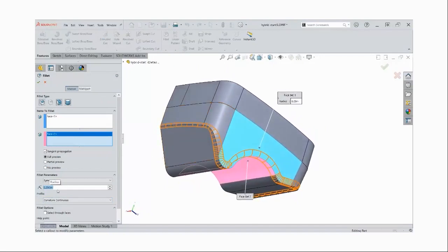So when you set the size for a fillet normally, it doesn't really look at the width of it, it's a radius. So if the angle of the faces changes, the apparent size when someone looks at it is also going to change. There's an option in here called chord width. It's only available when you're using a face fillet. And that actually maintains the chord, or the edge-to-edge measurement of the fillet.